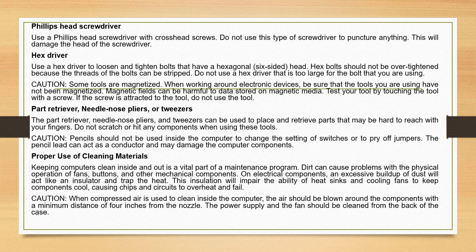Part retriever, needle nose pliers, or tweezers. The part retriever, needle nose pliers and tweezers can be used to place and retrieve parts that may be hard to reach with your fingers. Do not scratch or hit any components when using these tools. Caution: pencils should not be used inside the computer to change settings or switches or to pry off jumpers. The pencil lead can act as a conductor and may damage the computer components.